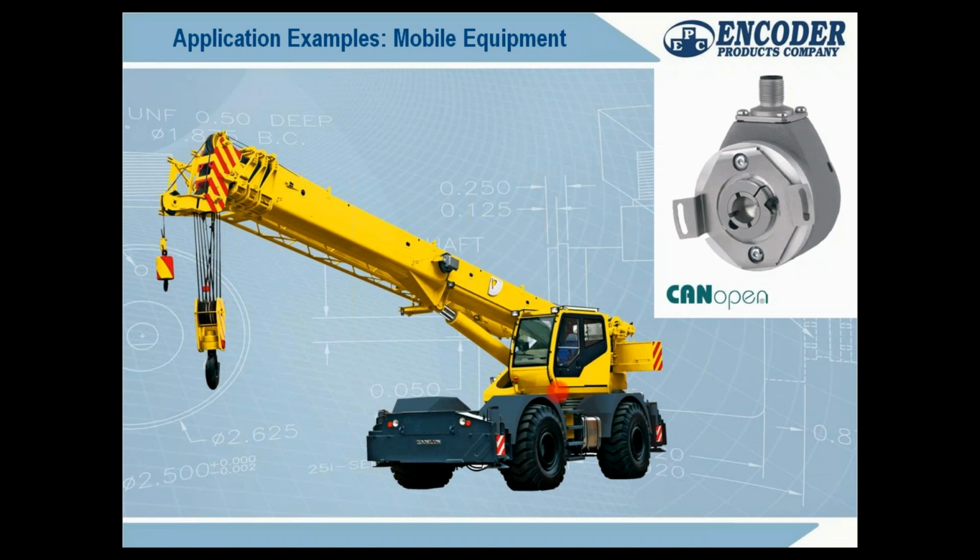Well, now they need a position of this superstructure for the software that controls it. You can actually set pretty cool false walls, they call them. If a crane operator is working between two buildings in a city, he can actually set false walls that limit the movement of the crane to help prevent an accident of hitting the side of a building. And to do that, the software needs to know the position of this superstructure. So there's an encoder of ours installed to give that absolute position.